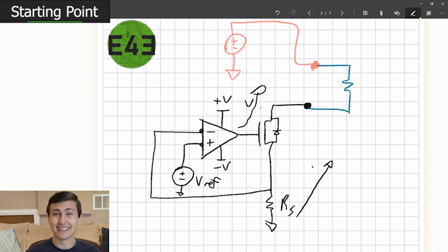Perhaps we can improve the slew rate or make it a little more controllable. Right now, we're just kind of getting the intrinsic gain of the op-amp, and maybe we want to limit that to something to control our slew rates. We don't really have that control right now, so let's add some of that control. Let's do it. I'm very excited.